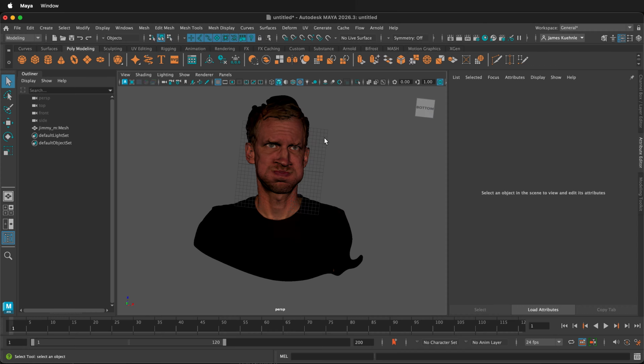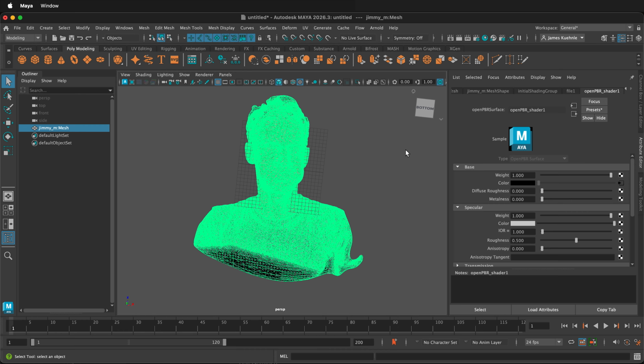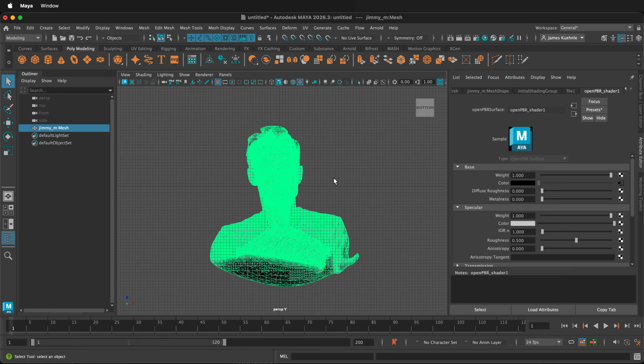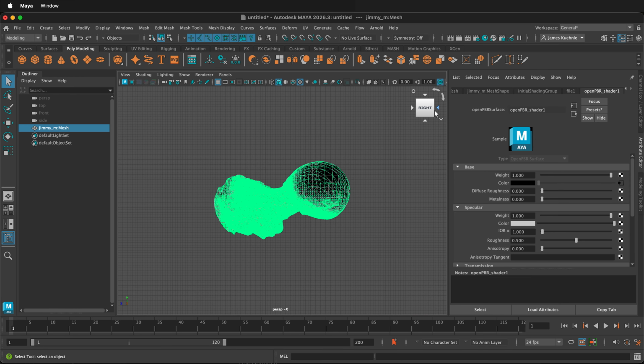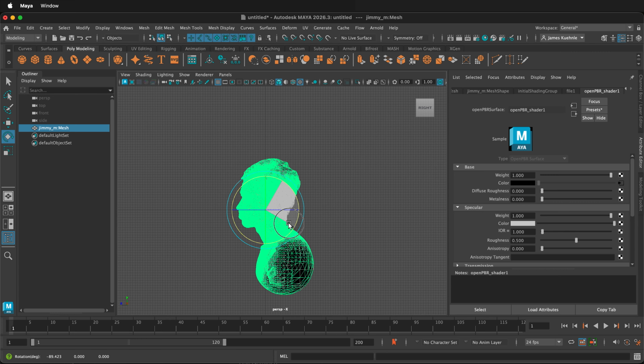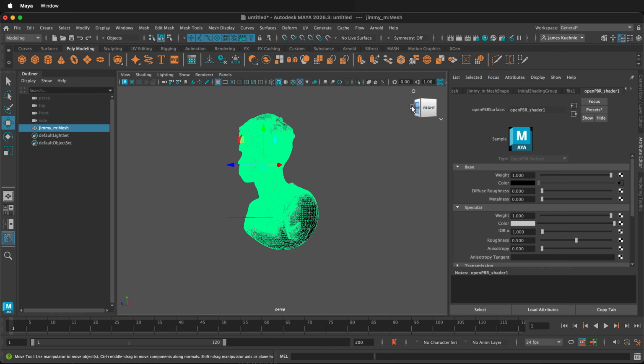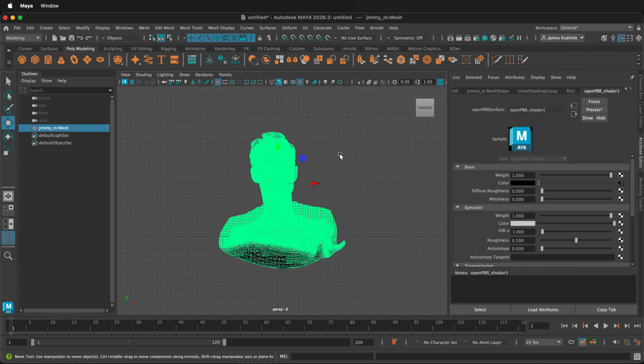In order to rotate this around and position it so you can edit it later, click right here and have orthographic view. That way we can really see what's going on. Click to the side here. This may be different for your particular scan import. I'll press E for rotate. And now I can rotate this to where I think it needs to be. I can press W to move it up. Then I'll rotate around this way with the view cube.